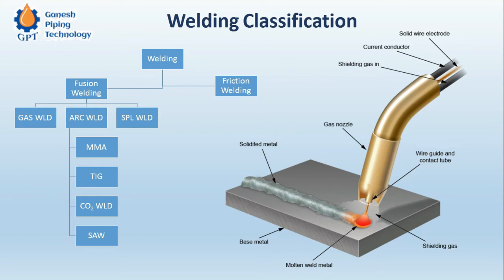Basically, we are not going to go into much detail, but just to give an idea, friction welding is basically two dissimilar components brought together, and a high degree of pressure is applied between the meeting parts, and there is a motion like rotation, so that because of this pressure and the relative motion, or because of some eddy current also, these two parts which are held together get welded. So that is basically friction welding.